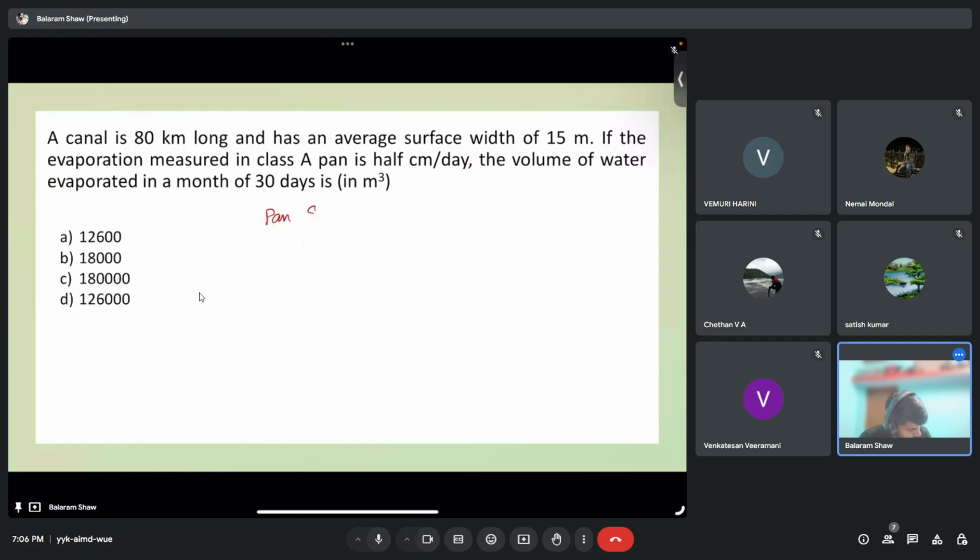If some groundwater discharge is happening, we can subtract that and get to the water budget equation. Second is the energy budget equation. If we consider the net radiation as the evaporation loss, then you get the total radiation minus the ground heat flux, whatever is there. All that you can just subtract and get to the evaporation rate or evaporation loss.